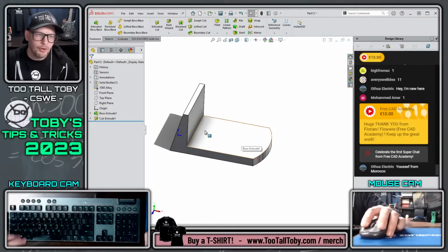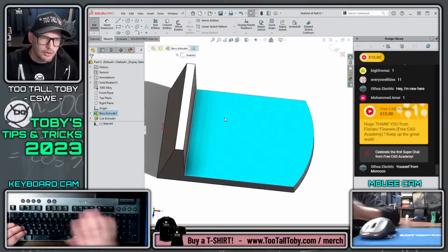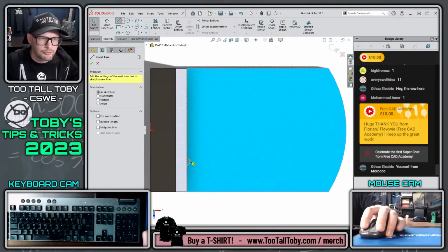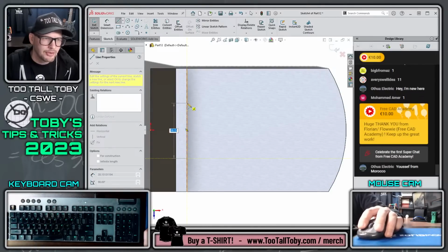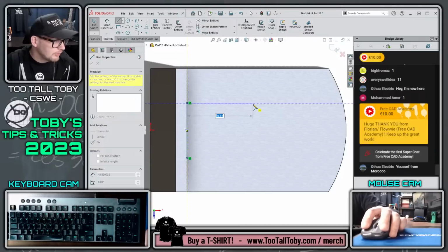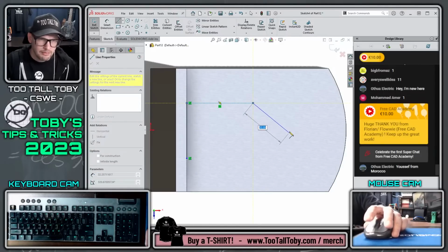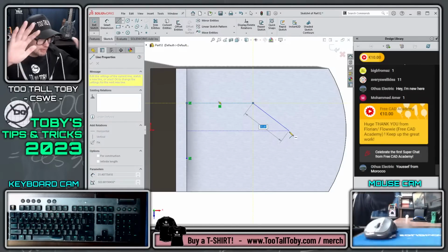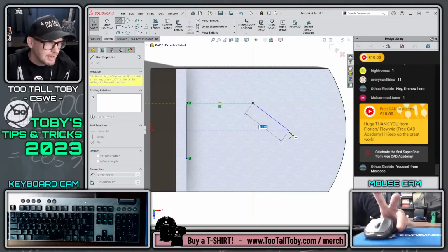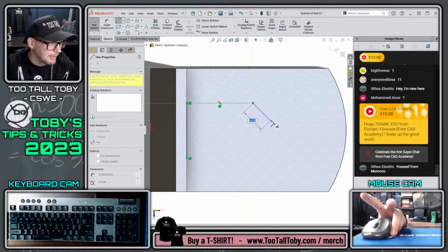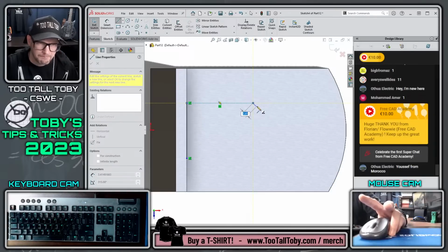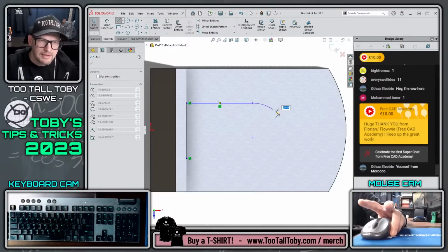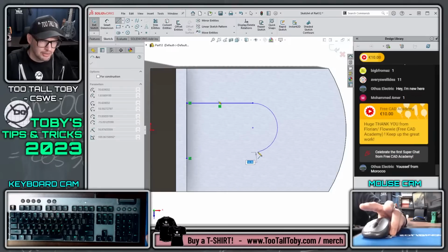So on this topic of auto dimensions, we can do it with arcs. We can also do it with the line arc line workflow. So if I single click, I move my mouse over in this direction, single click over in this direction. Now I just single click the button here. You notice I just let go. Now I'm not going to click anything, but I'm just going to move my mouse until it's over that endpoint. You can see that this brings me into an arc command.